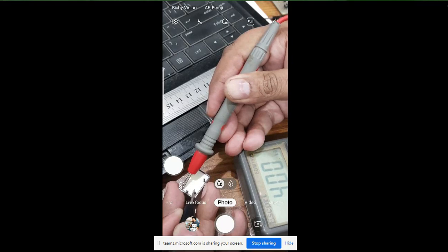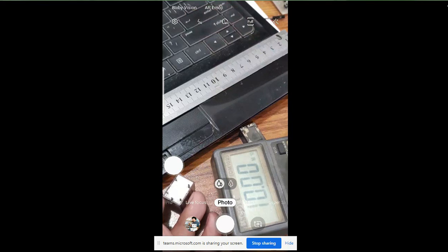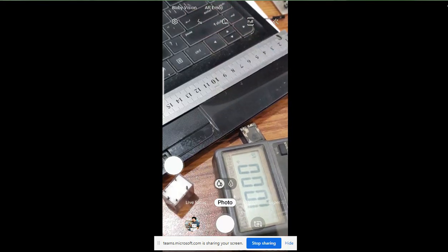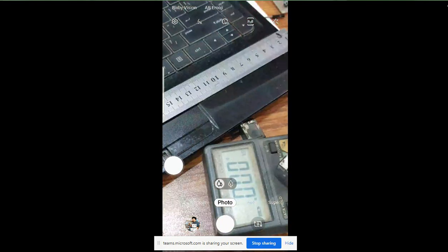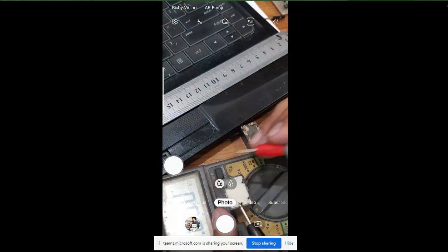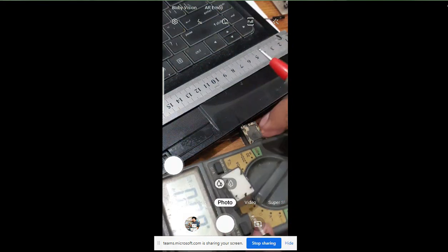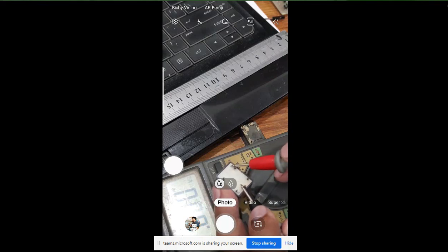You can calculate the current yourself, because this is going to be 12 volts. Now I want to check the continuity test, as you have already done before, so let me place this on this one so everyone can have a look. Okay, so when I contact this pin, first of all just checking my meter, this is not buzzing, this is buzzing. So this means that these 2 contacts are in contact with each other without energizing, and when they energize, this will beep on.